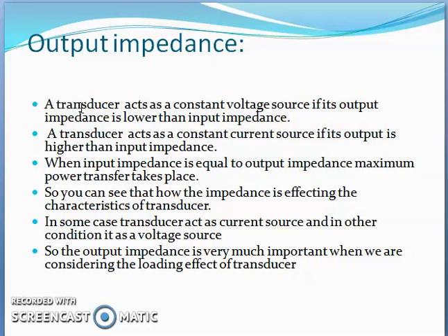So you can see how the impedance is affecting the characteristics of the transducer. In some cases, the transducer acts as a current source and in other cases, it acts as a voltage source. So the output impedance is very much important when we are considering the loading effect of the transducer.